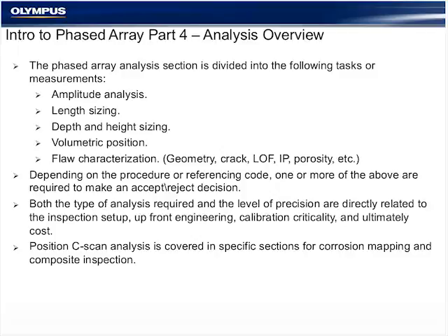In fact, as a service technician working with customers, the overwhelming majority of data I see typically has more mechanical acquisition problems than software or calibration, meaning that the probes were not adjusted well, the mechanical carbides on the feet were not positioned well, some of the scanner mechanics may have been loose.